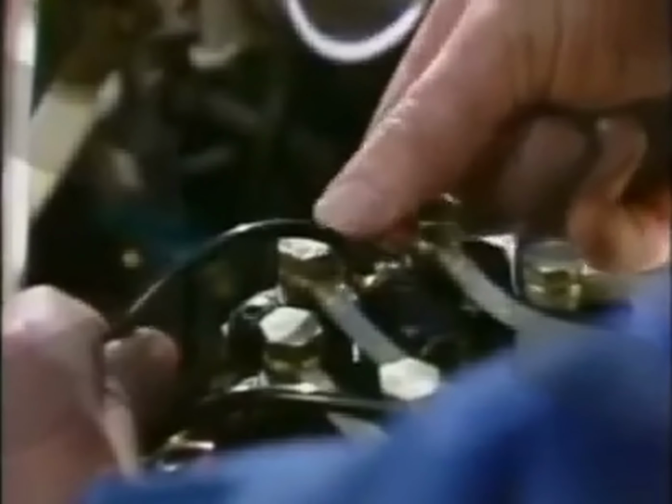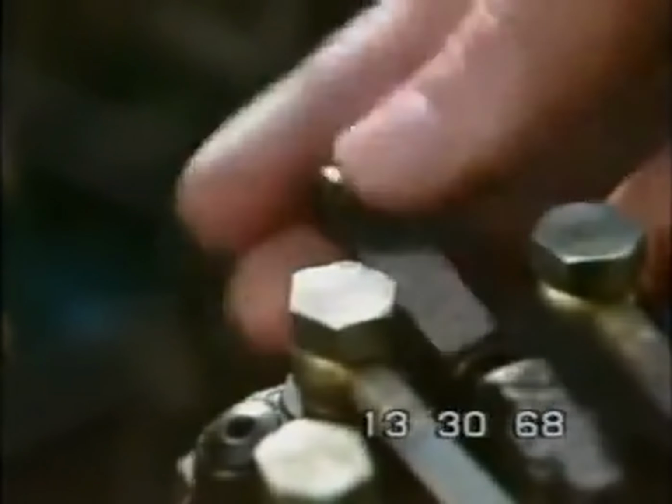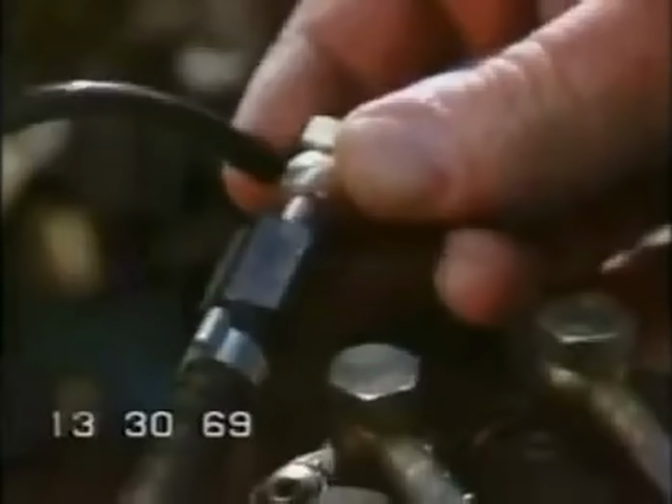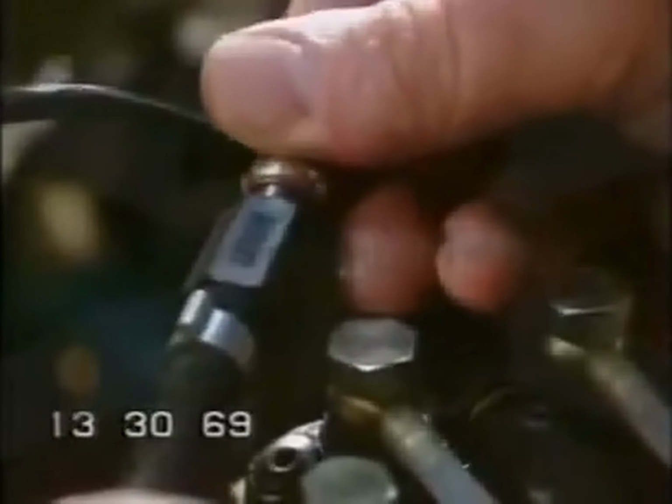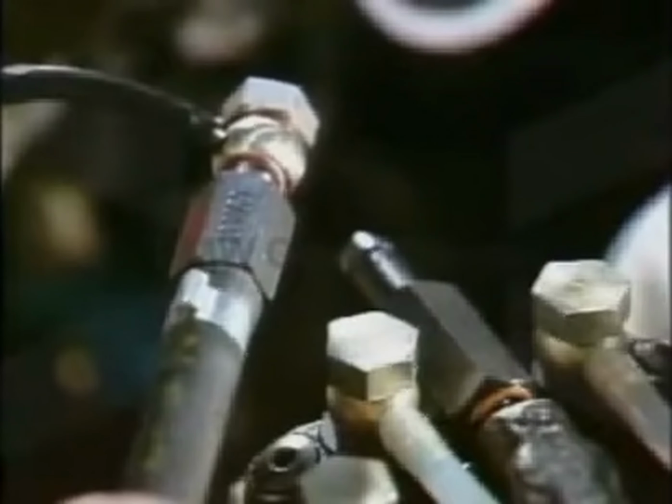To check the primary pressure, we unscrew the pressure pipe leading from the fuel distributor to the warm-up regulator. The tools required are this and this testing connection. And the 10-bar pressure sensor. One end is screwed to the fuel distributor. The other to the control pressure pipe of the warm-up regulator.